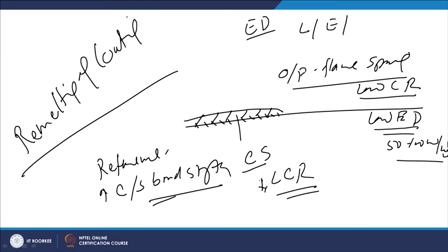or electron beam or the TIG arc or the plasma arc, those heat sources can effectively be used. These heat sources are applied onto the already coated surface developed by flame spraying. This will cause controlled melting of the coating, either only the coating, or the coating can be melted along with the substrate up to the interface, so that unnecessary dilution is also avoided.